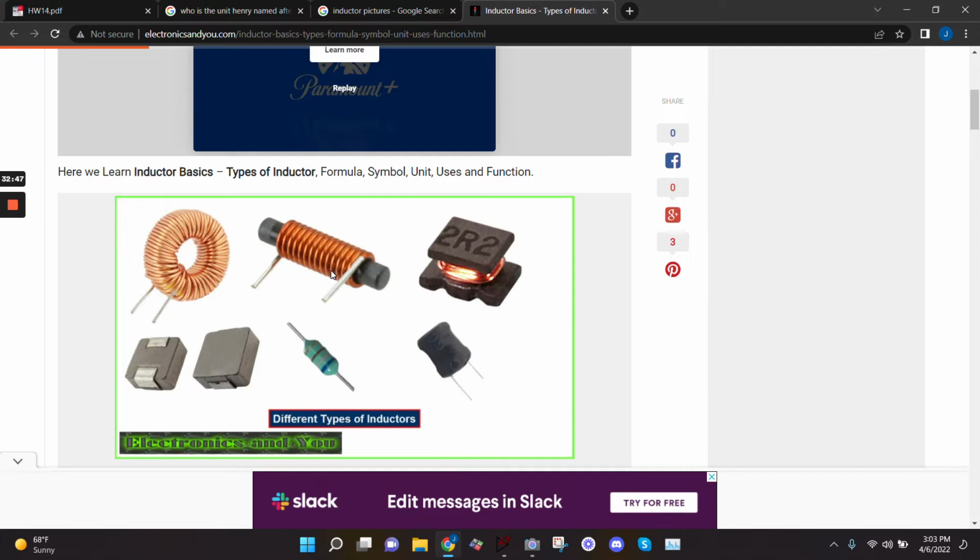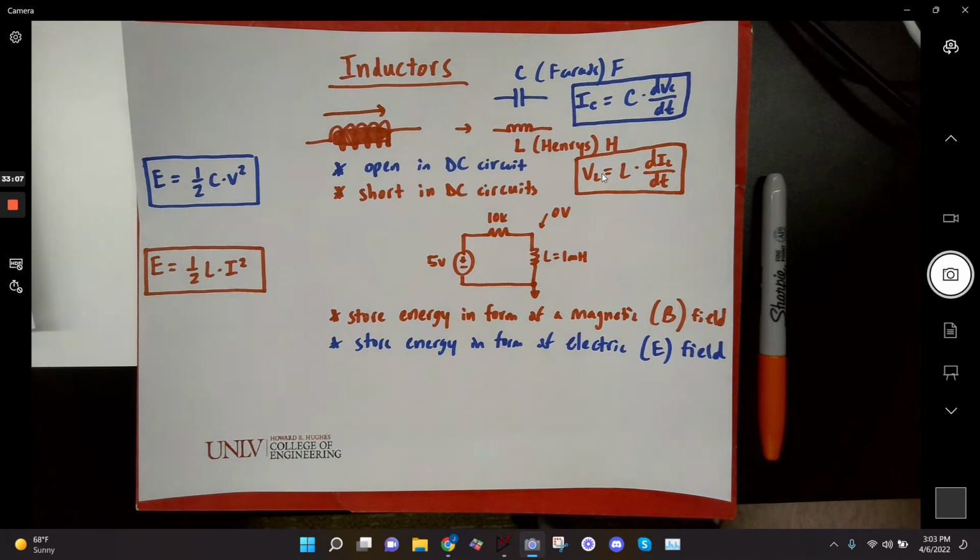For those of you who don't know, they're basically used to generate from some low voltage. They can be used to step it up to some higher AC voltage, and from a higher voltage, they can be used to step it down to some lower AC voltage. But the key, I keep saying AC, you can't use DC voltages because you need the changing current, right? Like I wrote down over here, voltage across the inductor is generated by a change in current. If there's no change in current, then the voltage across the inductor is zero and it just acts like a wire, right?